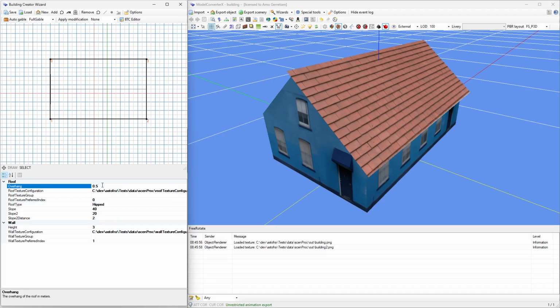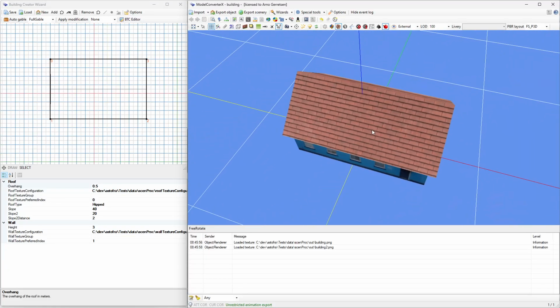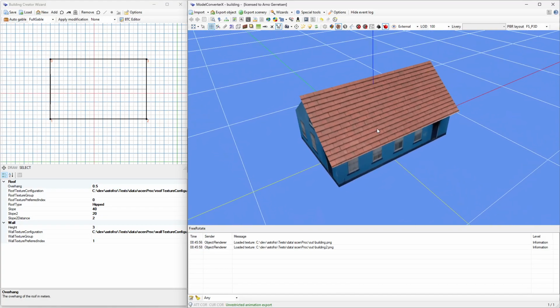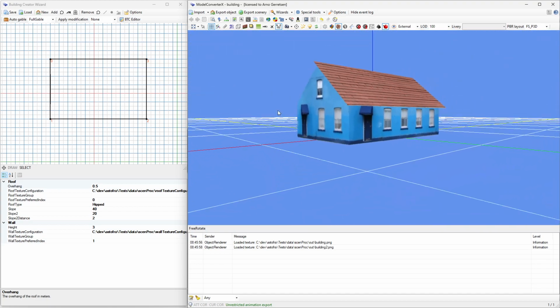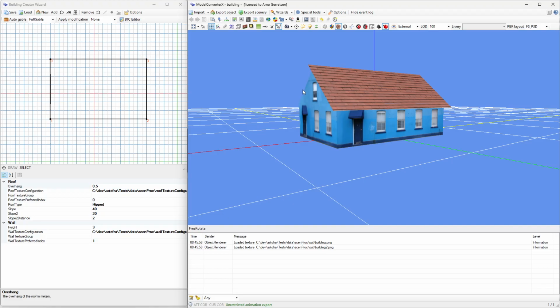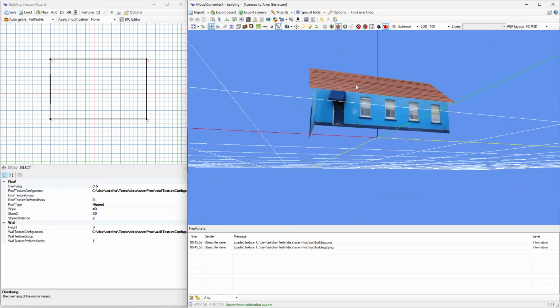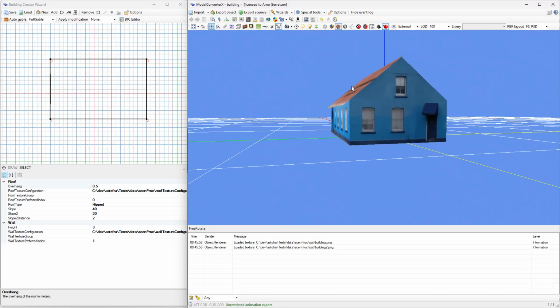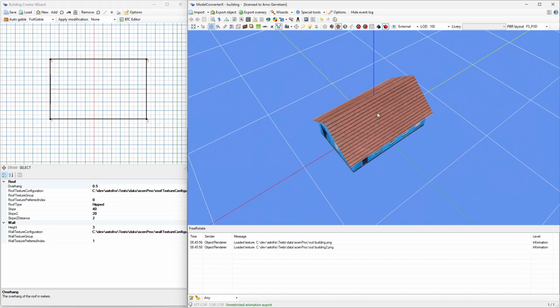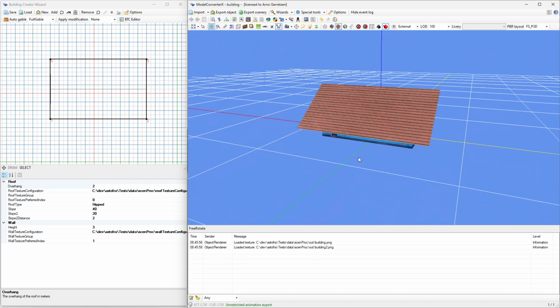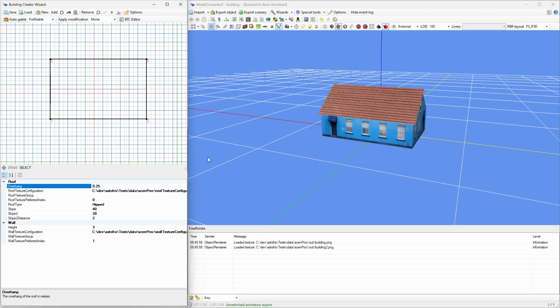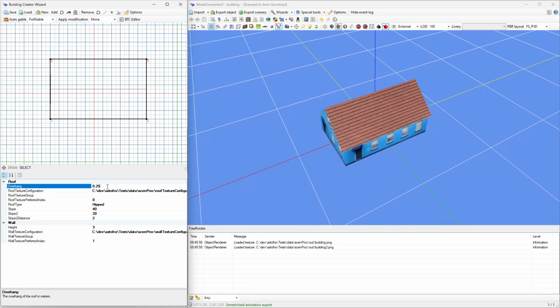With that, if I put it at 1/2 meter, I can have the roof slightly bigger than my building, so that it has a bit of overhang compared to the walls, which can look more realistic for certain areas in the world. And you might already see if I pan around, to keep the number of polygons low, I've decided to not render the underside of the roof. So only the top side is being rendered. So if you get very low, it might look a bit weird, but since buildings are typically mainly used from the air, it can be a useful function to make the buildings look a little bit more realistic. And of course we shouldn't overdo it. If we give a huge overhang, it doesn't look realistic anymore. But if you keep it to reasonably normal sizes, you can get slightly more realistic looks than with the default of 0, which might look a bit simple.